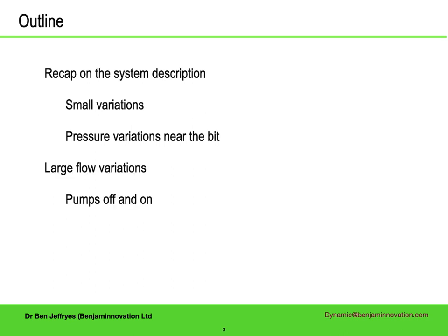Then I will look at the full nonlinear system and show you what happens to downhole flow when the pump flow changes a lot, for instance, when the pumps are started or stopped. Finally, I will show you how to reach a stable downhole flow a lot faster.